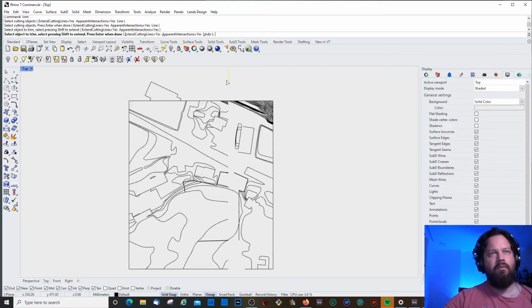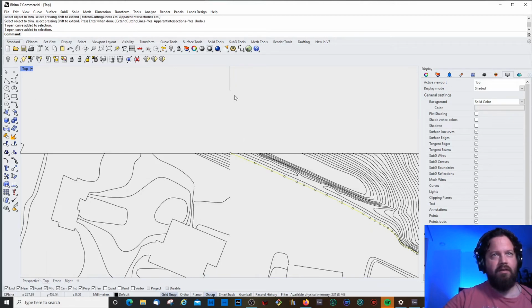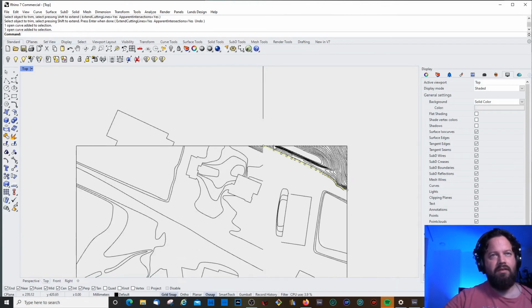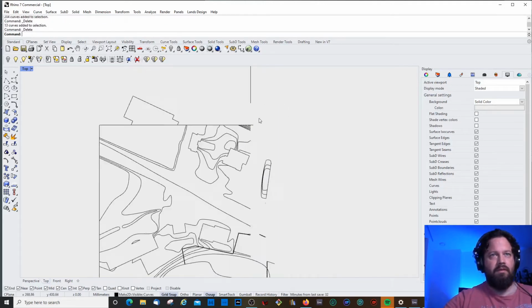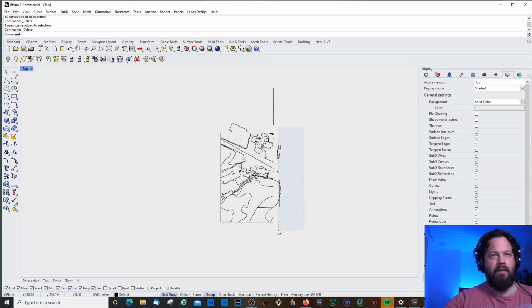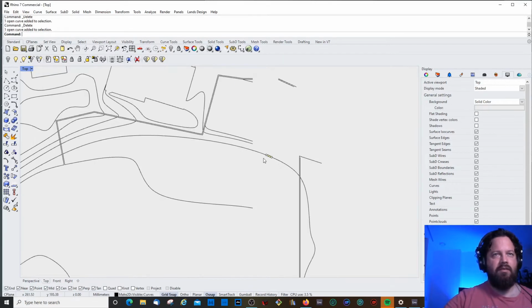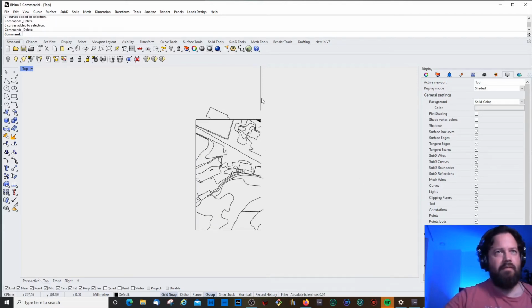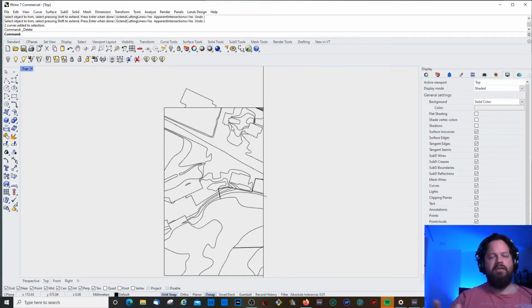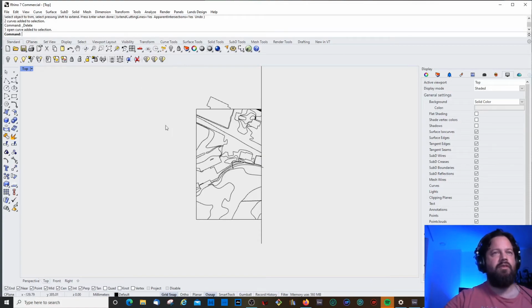Then it was cutting everything which is actually overlapping from the extension of this curve or this line was cut away. Not these ones because they are actually stopping here before that extension. Yeah, I could then do this. Interestingly, it hasn't cut these because these are all like small separate arcs. But yeah, it's possible. So if you have big drawing sets where you need to cut out something, then you can use the trim function. It's very useful. It also works with surfaces, of course.